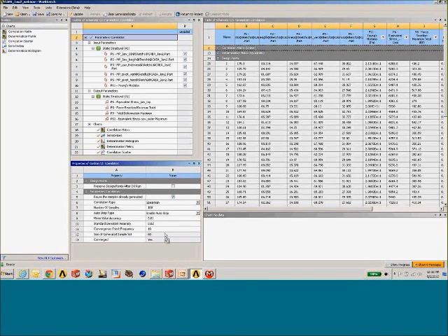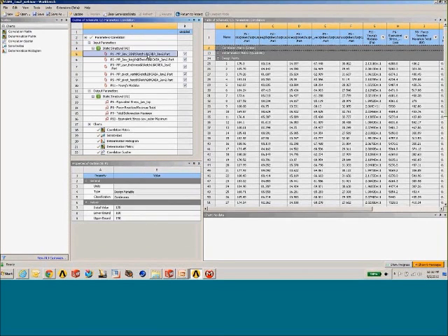It was able to determine that a lot of the variation that I was asking for was not required. So that's the setup of my parameters correlation. Next, I go to the individual parameters themselves, and I specify the range, the upper and lower bound that this parameter could potentially see. Now, this is actually a very important part of setting up a robust parametric model, because you're not necessarily guaranteed that a particular design point that you've specified with a particular parametric value is going to regenerate on the CAD side.